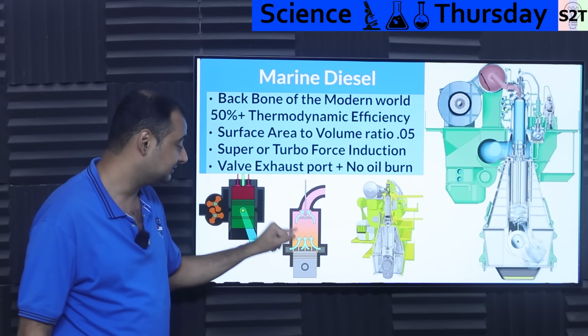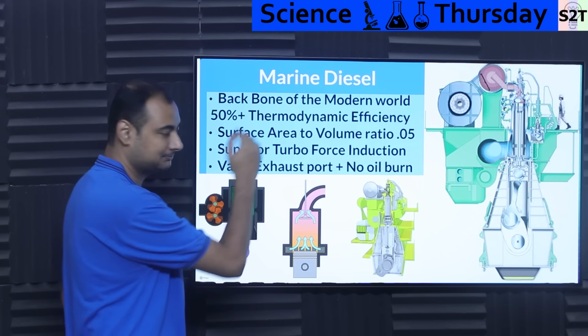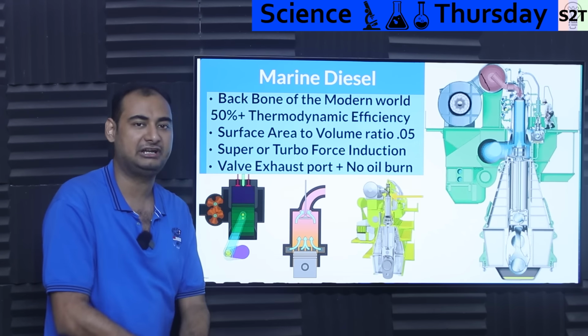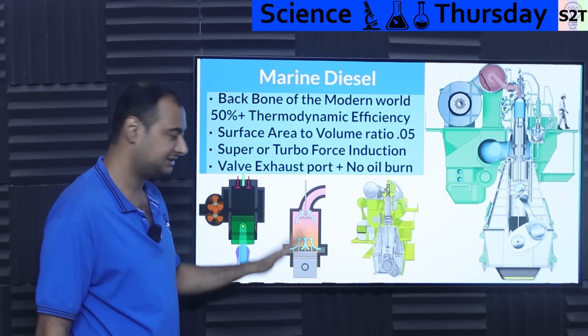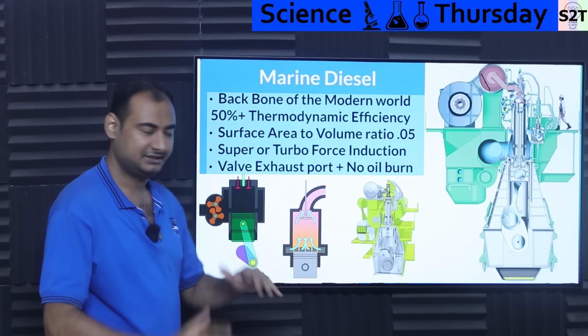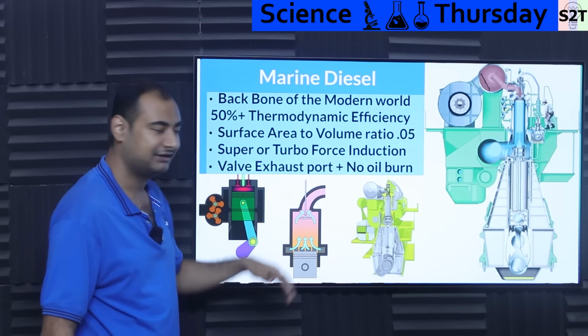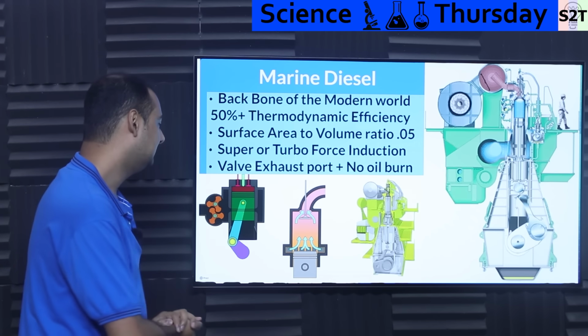Now, why do you want to do this? It is what we call uniflow scavenging, meaning you flush everything out from bottom to top. Basically, the piston goes in, you just flush everything out. Fresh air comes in, everything flushes out. So that's the awesome part. There is no mixture, there is no mess. It's clean. And you have a valve there because again, you have a combustion event. So the valve is handling the combustion event, and then you open it up, everything goes away.